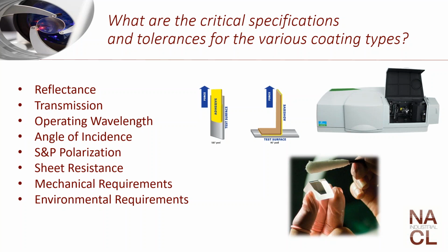Again, tape adhesion, abrasion. There's tensile strength measurements, all different sorts of things. Pencil hardness is another one for dip, spray, and spun applied coatings. That's basically just telling you how hard the coating is on an H level. Typically plastics reach maybe 4 to 6 H, whereas glass and others go much higher in the hardness rating.